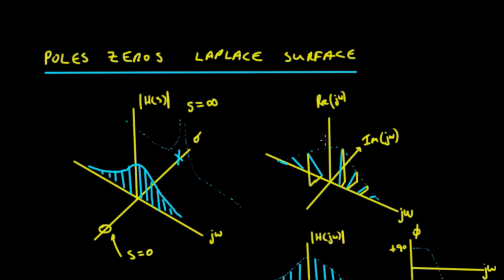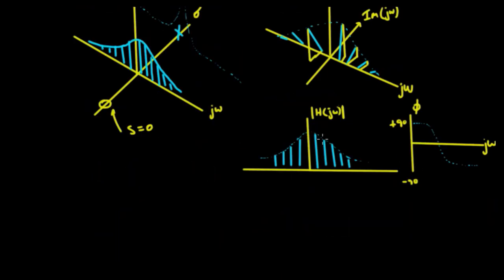But of course we don't draw it in 3 dimensions, we always put it into an easier to understand 2 dimensions, which is the magnitude of these blue lines here. The magnitude really is, by Pythagoras, this distance squared plus that squared, and the root of it will give us the magnitude or the height of these phasors.